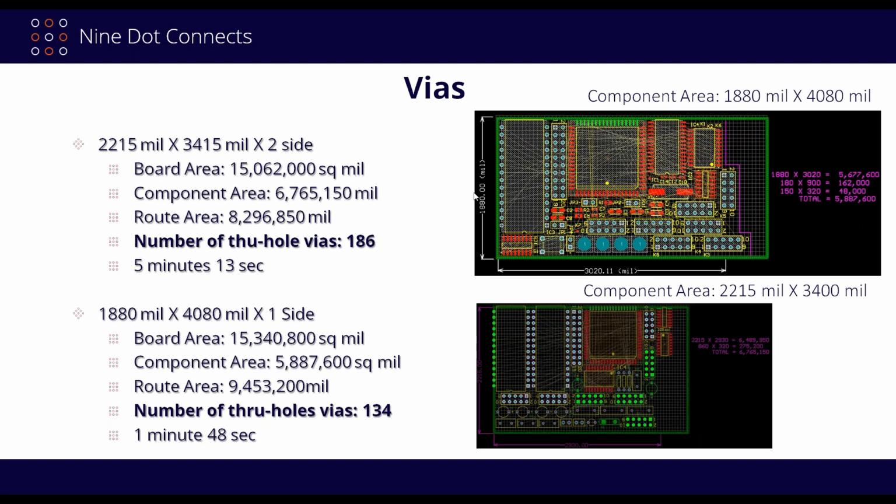His board looks a little bit smaller than mine. What happened? When I started doing the analysis, I really found that his board area and my board area weren't too far off. And neither was the component area or the routing areas. But he had far less through-hole vias. That causes a lot of obstacles in the end, so that was a factor to play in there too.